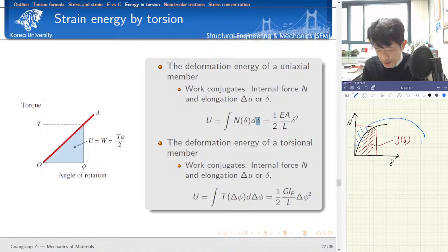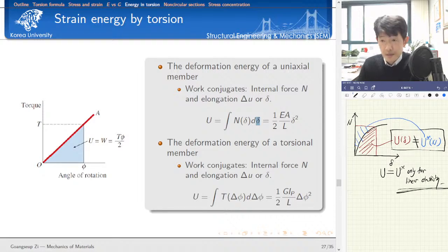In this case, even with our naked eye, the complementary energy as a function of the actual force is not equal to the deformation energy, okay? The numeric values are not the same. This is a general case. The numeric value of deformation energy is equal to that of complementary energy only for linear elasticity. Okay, so please keep in mind this point.